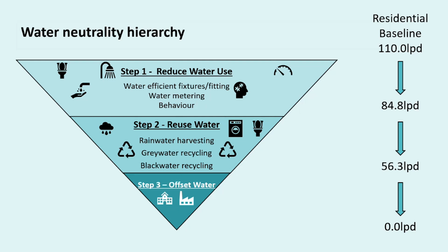So as you can see, water neutrality strategies are not simple and straightforward. They're very involved and they are also very expensive and time consuming. While some small developments might be able to mitigate demand by retrofitting a handful of homes, the large scale schemes mean that they need comprehensive strategies, and they can be time consuming to develop, particularly if groundwater boreholes are required.